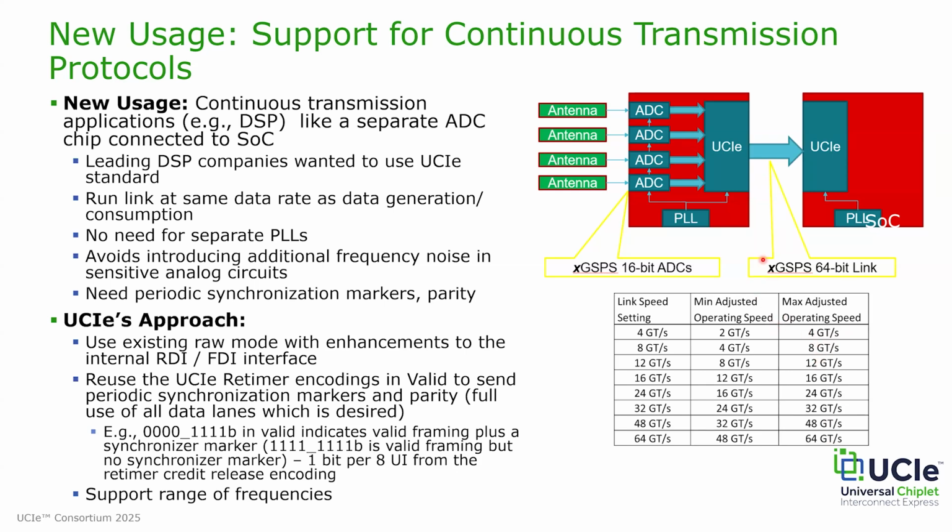They might have something like, let's say, I'll pick a number here, 3.9 gigahertz, that they want to operate on. In that case, we can always put in another PLL and an elastic buffer here and then send the signals across. But these are very sensitive analog circuitry, so that can cause noise in there.